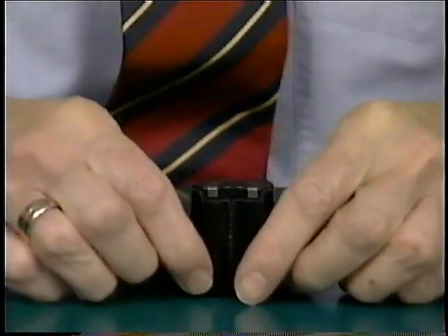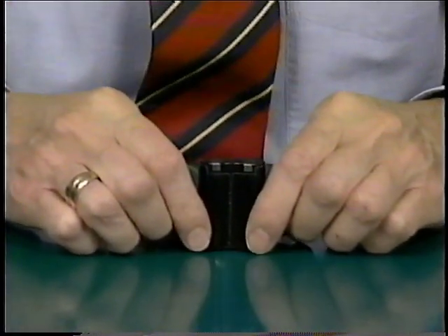But battery testing is extremely important, particularly with lithium batteries and the new electronic cameras. If a camera comes in not working, always suspect the battery first. And it's important, particularly with lithium batteries, that they be tested on a battery tester which is rated for those lithium batteries. A conventional battery tester will often test a lithium battery good when in fact it will not operate the camera.